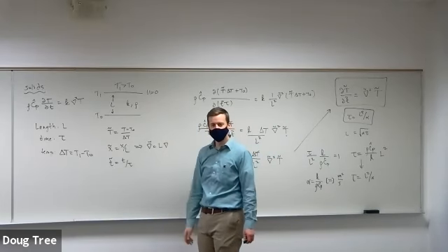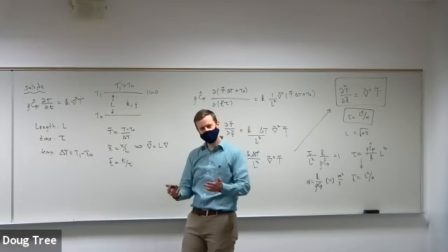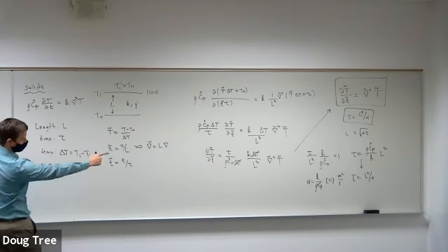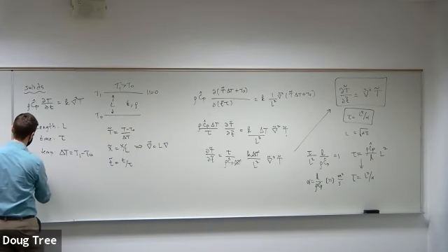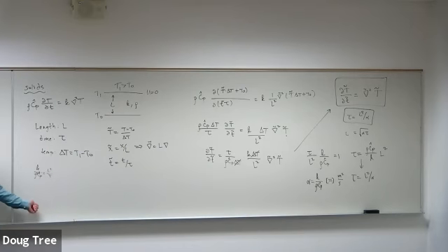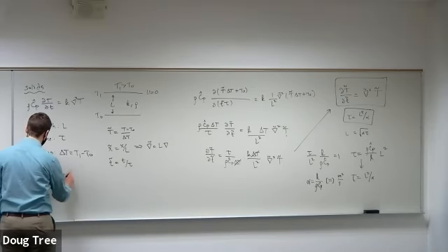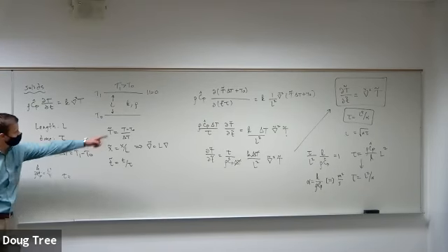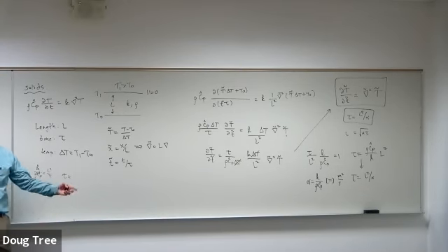I could have told you. I could have said instead, how do I get a time scale? And I could have said, well, I have a diffusivity, right? I could have argued the other direction. I could have said k over rho c sub p hat is a length squared per time. And I could have said, let me pick my time scale to be this, and argued backwards from that. And then I would have found that the dimensionless number was 1. I wanted to motivate it differently.